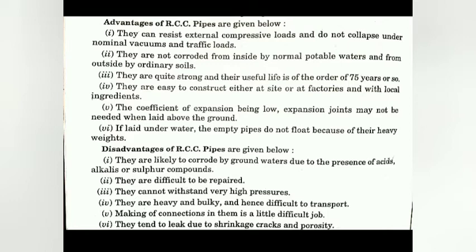traffic loads. See, they can withstand the compression that is coming in the roads when they are used in the roads. They can withstand the compressive pressures, compressive stresses, and also the external loads that are coming on them. They are not corroded from inside by normal potable waters and from outside by ordinary soils. They are neither susceptible to the effect of the water nor to the effect of the soil because they are safe. They are quite strong and their useful life is of around 75 years.